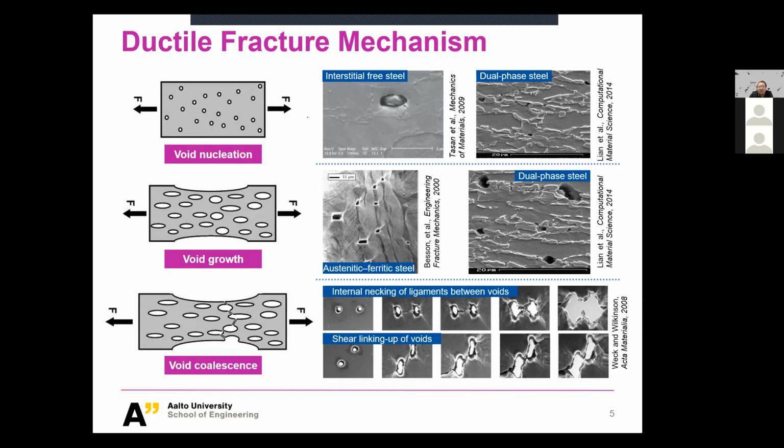Brittle fracture starts from local. So it starts from, let's say, one point, which is the weakest, or which is the point that reaches the K1C value, if we use fracture mechanics to describe it. And that kind of local crack will suddenly become unstable, and it just goes like that. And then you get your brittle fracture.